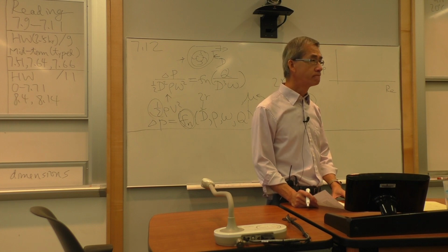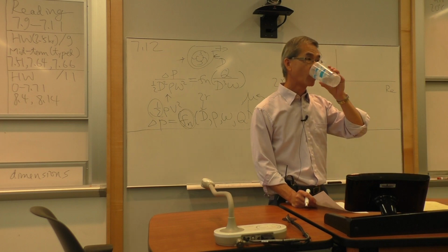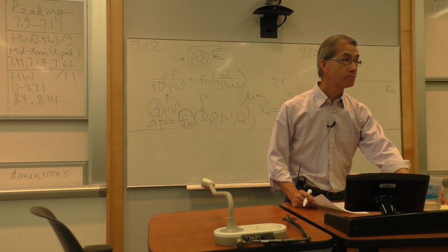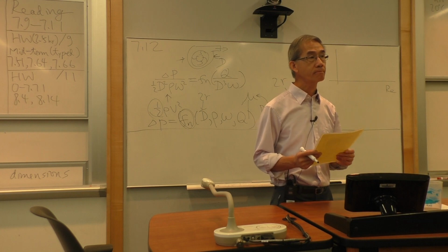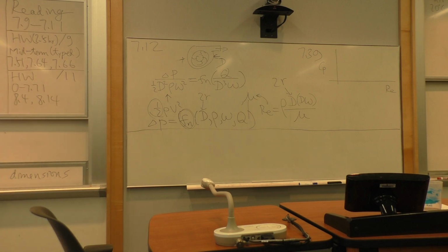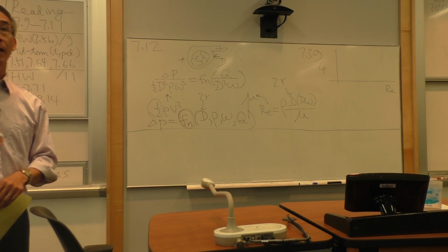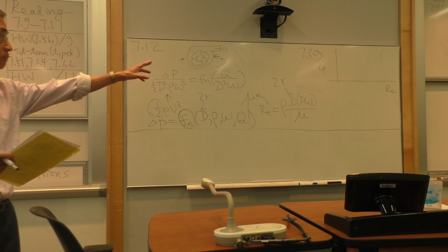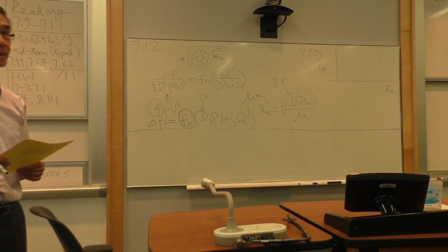Yep. So just for clarification, when you're solving for your pi terms, you pick like 3 different variables, and you can't like take them, you know what I mean? Do those have to be on the right-hand side of the equation? They always will be on the right-hand side of the equation, because you use the independent variables, 3 of them, on the right-hand side to form those pi terms. And after I went through this pi problem, I have a summary of how to do that one more time. But as you said, it has to be on the right-hand side.